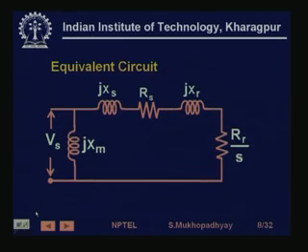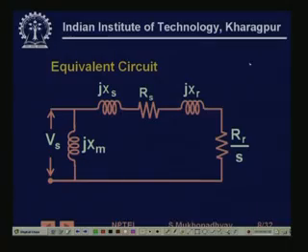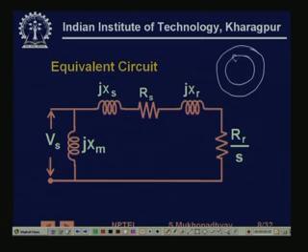So, what happens before we see the equivalent circuit is that there is this stator and there is this rotor. The rotor also has coils. And there is an MMF which keeps rotating with this angle, continuously and fast, at some speed which we call the synchronous speed. So, naturally, what will that do? It will induce EMFs in the rotor coils.